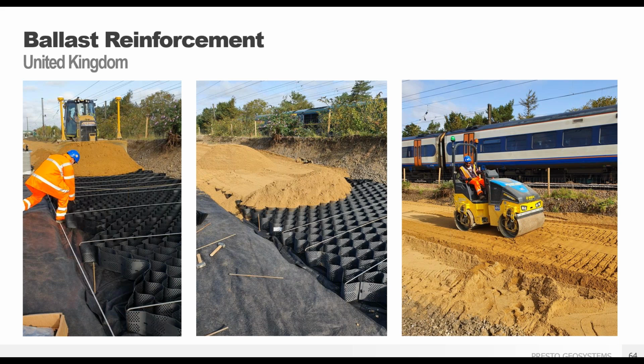When you're compacting a GeoWeb, you want to make sure that you really just use the roller. And if you need any kind of vibration, make sure you use really light vibration, because typical contractors a lot of times will want to hammer the vibration. But with the geocell or GeoWeb panels, you can actually sometimes move those panels right out of the subgrade. So if you're on site with construction, start off with just a roller compaction, and if needed, just a light vibration.